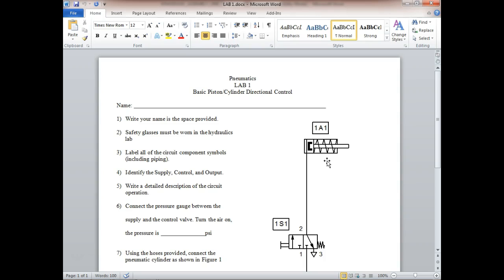So how many positions can a hydraulic valve have? Two to three. How many ports can they have? Two to five, right? You understand? Or how many ways can they have? How can they be actuated, manually or automatically? The symbols for the valves are exactly the same. Of course, you can't use a pneumatic valve in a hydraulic system. Well, it might work for a little while. But the problem is we've got so much pressure, and usually the mechanics and the levers don't give us the ability to move that amount of pressure around.